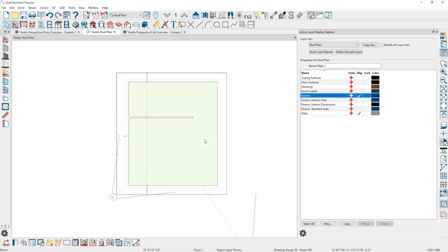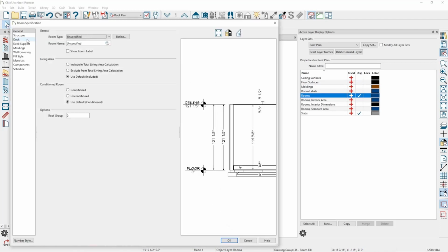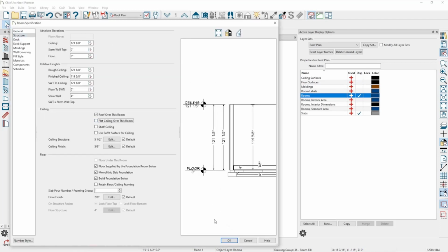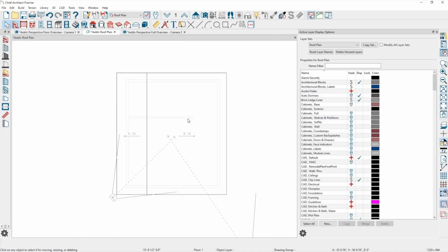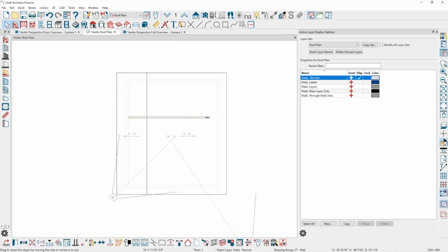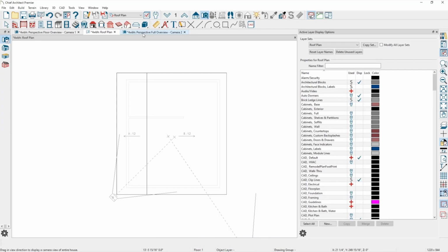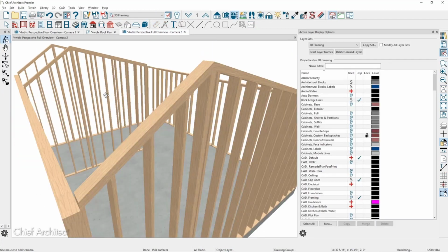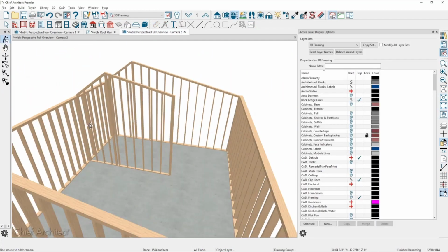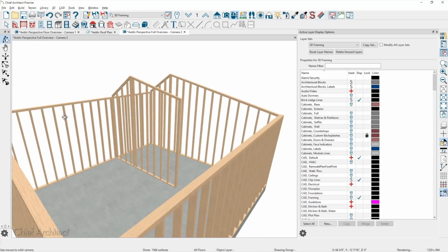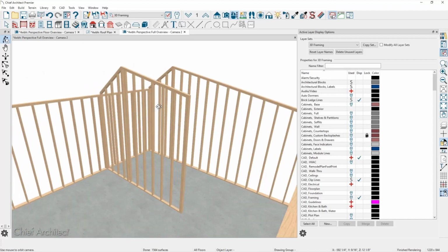Before I connect that, if this room does not have a ceiling in it, so let's pop the ceiling out, right? So it's got that, and then we pull this wall back. Well, let's just leave it open, and we should have automatic framing on. Let's go back into the framing deal. It should follow it. Okay, I must just not have done the balloon setting correctly, because that's exactly what I'm trying to accomplish. Okay, good.